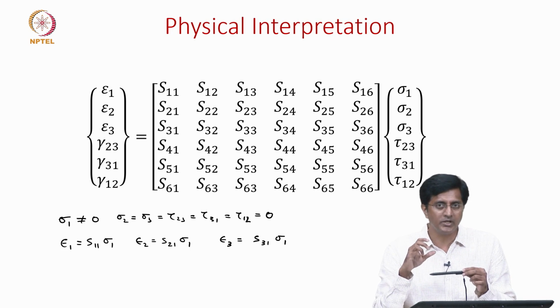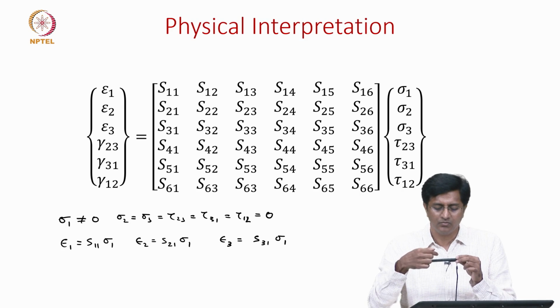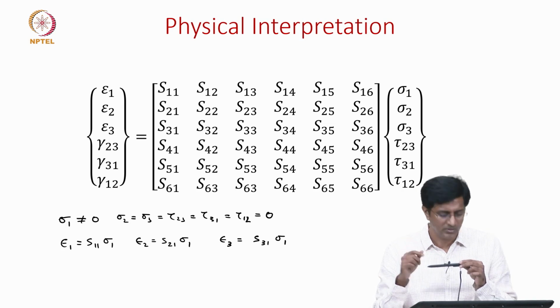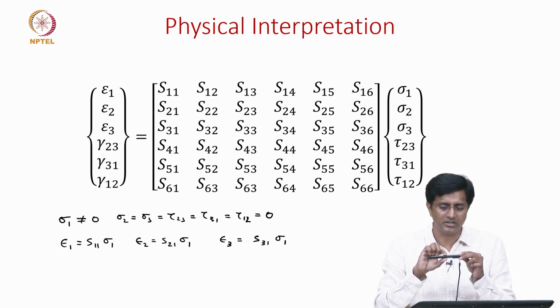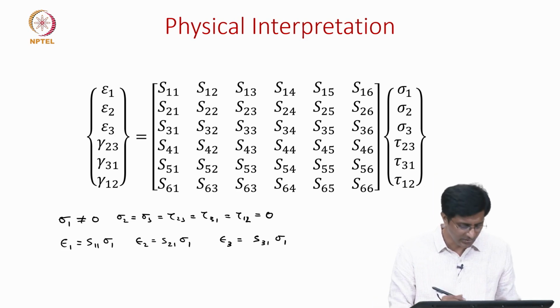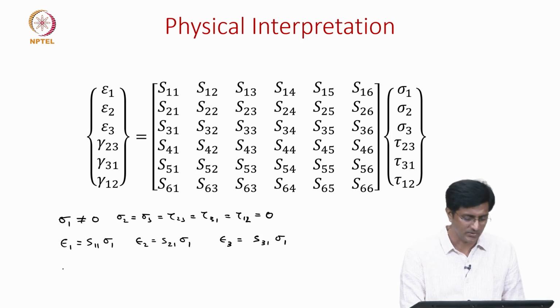For an isotropic material too, we see a change in dimension, but the changes in direction 2 and 3 are the same. For an anisotropic material, the change in dimension in the second direction is different from the change in the third direction. But in addition to this, we do have the shear strains as well.